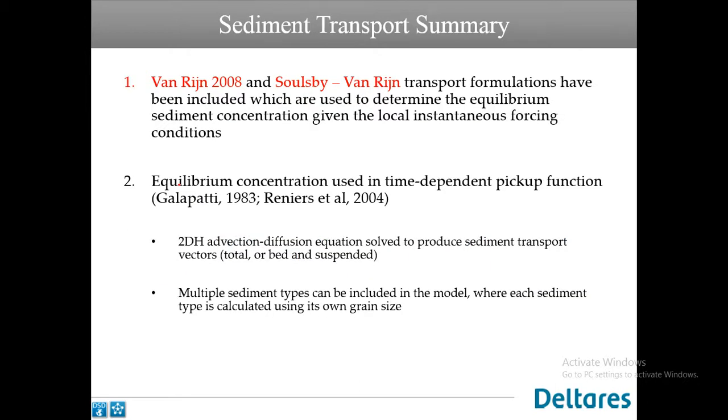Okay, and for the summary, just to give you a summary of everything you learned about sediment transport. Sediment transport is quite a very huge subject to cover. It's not going to be enough just for a simple explanation. But as an end user of XBeach, you just need to know that sediment transport in XBeach is basically being governed by two formulations, Van Rijn and Soulsby-Van Rijn, to determine the equilibrium sediment concentration.